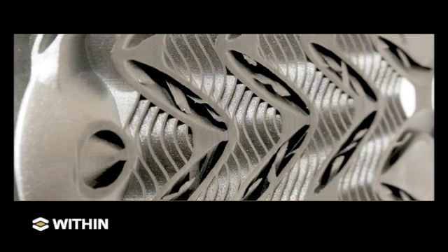Now, looking at the insides, inside the tubes, we've created an obstacle course of turbulators. This is used to turbulate the internal fluids, because as the fluid runs through a channel, what ends up happening is the hot fluid will continue to run through the center while the cool fluid is nice and cool around the outside, and you have what you call laminar flow, which isn't good because you're not being very efficient. So having an obstacle course means that as the fluid runs in, it's constantly being tumbled, and you have more efficient heat exchange. So we were able to manufacture heat exchangers with these obstacle courses within the tubes, 3D printed in one piece, in one build.